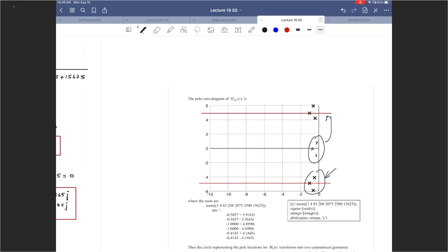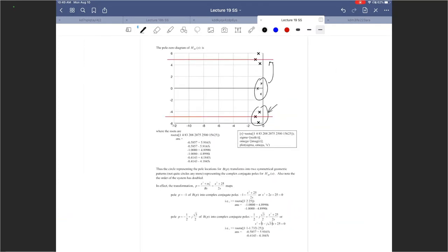And the discussion that we just had is essentially written up, and the corresponding MATLAB code is also provided. If you want to experiment with that in MATLAB, feel free to do that. But that's essentially how you would transform a low pass Butterworth filter, for a particular order, into a band pass filter, given the center frequency and the bandwidth of the desired band pass filter. All right.